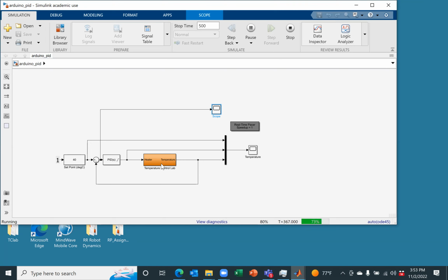And then finally, you fine tune the value of I so that steady state error goes to 0. But once you start adding I, you will see there might be some overshoot or some sluggishness in the response. At that time, you have to adjust just the P control. So this is the iterative process that you have to follow to tune the PID gains in actual practice.